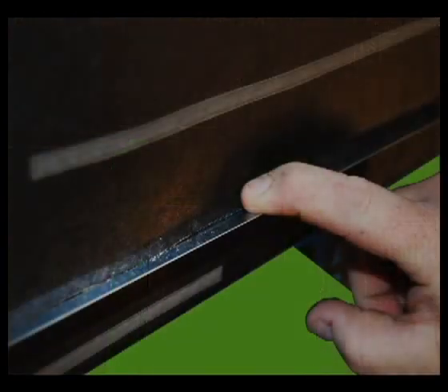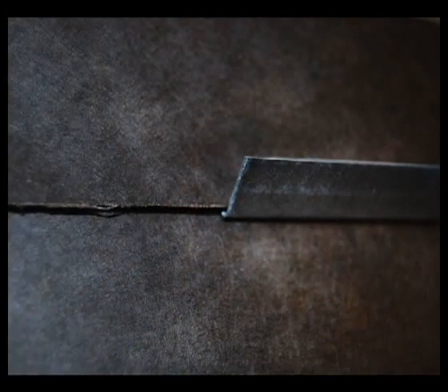Install flashing tape to cover the back flange of the moisture diverter and run onto the wall sheathing. After the moisture diverter is attached and flashed properly, install the next course of the WRB, making sure the WRB is bottomed out in the trough of the moisture diverter.